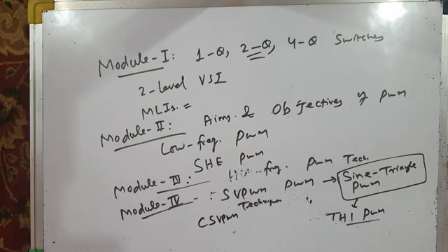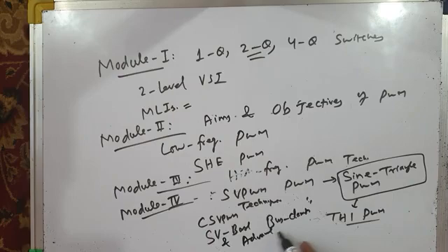And then I discussed with you space vector based bus clamping techniques. Conventional space vector PWM technique is also a continuous PWM technique, whereas space vector based bus clamping techniques and space vector based advanced bus clamping techniques, which we studied in details, are discontinuous PWM techniques.